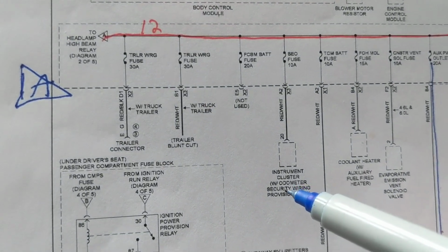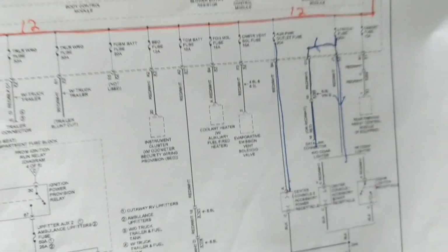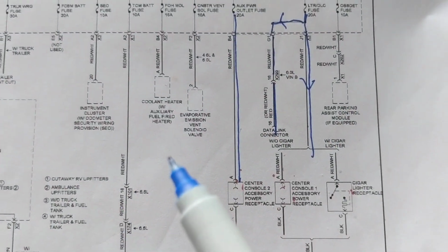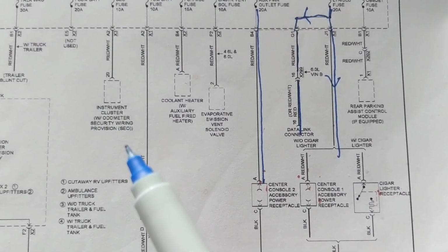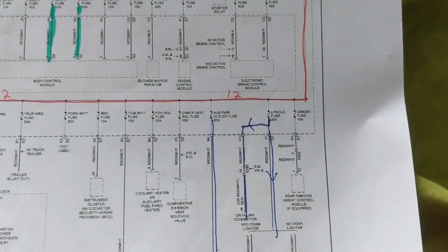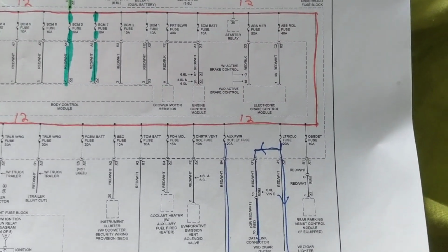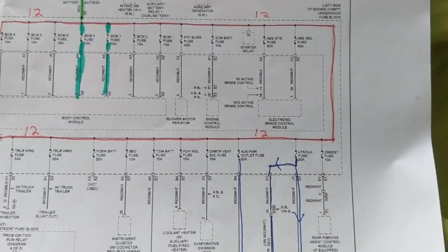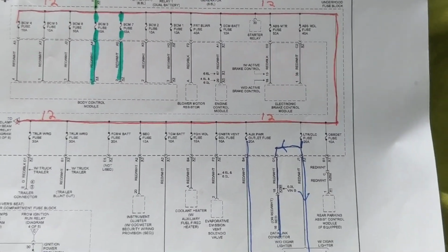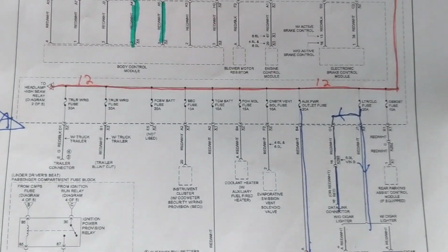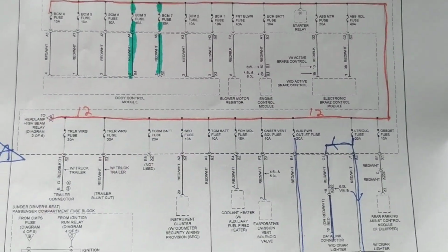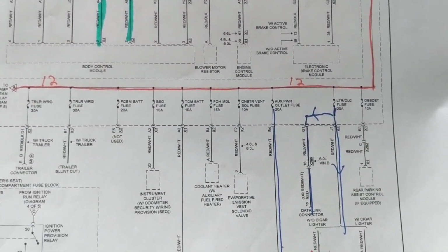Okay? Now, a couple of other things. Look how many modules are involved. A lot of modules, a lot of units. When troubleshooting, and I always get asked this a lot, the first thing that people have a tendency to do is, let's go check the fuse. You start off with the simple things. True. However, not everything in automotive diagnostics will be the fuse. I wish it was, but it's not.